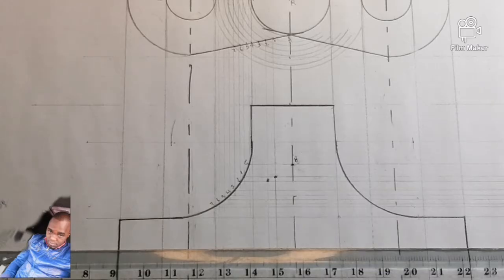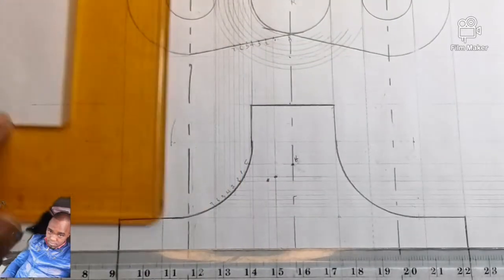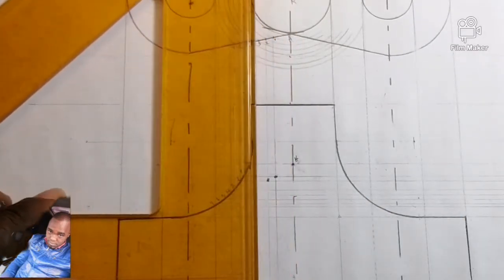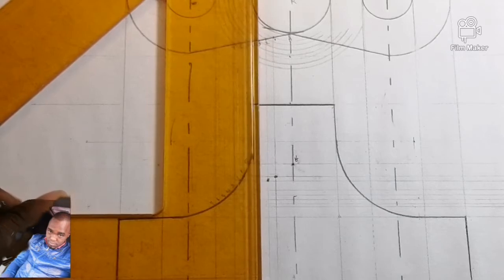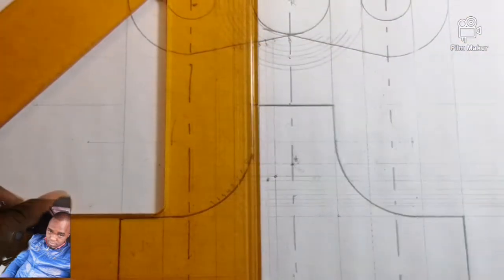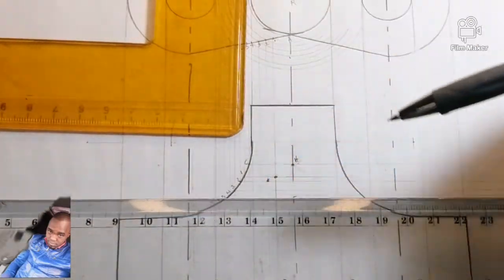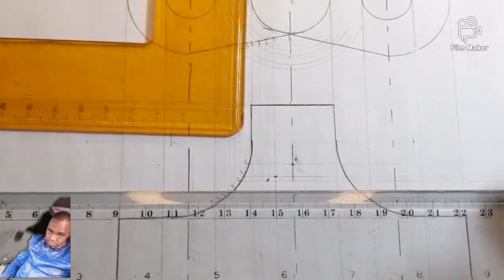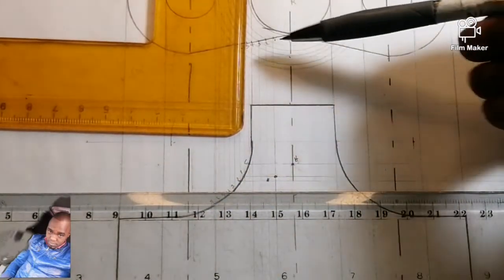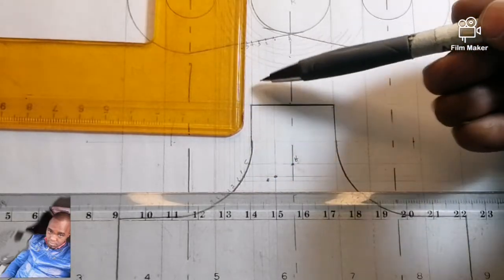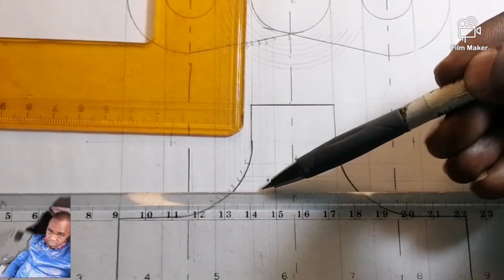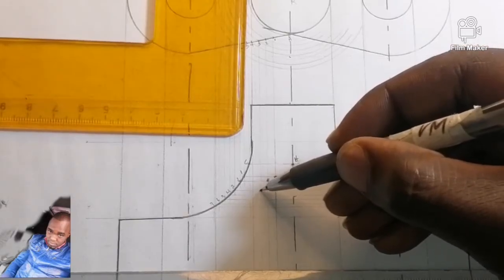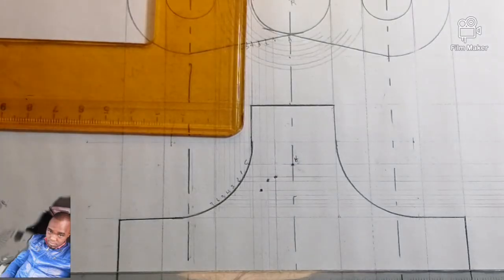Yes. So let's go to point 3. Right from our top view, it goes down to our front view. This is point 3. This is the line of 3. Trace. This is 3. Remember, see? 1, 2, 3, isn't it? So this is the line of 3. So it must intersect with the new 3. There it goes, which means I've got a point here. You understand? I've got a point there.